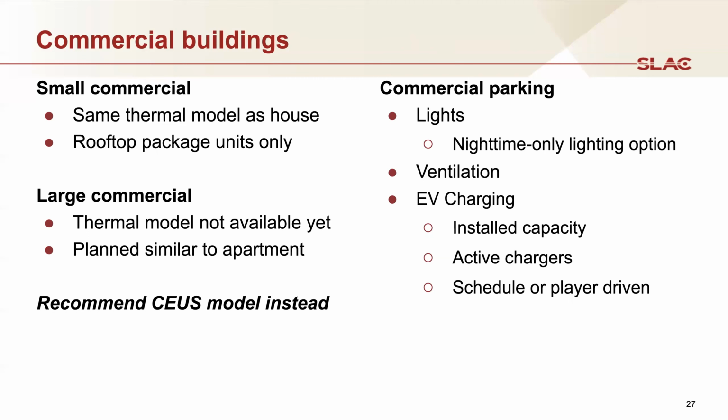For large commercial, we don't have a thermal model yet for large commercial buildings. We plan to do something similar to apartment buildings, but for now, I would just recommend using the CUS data models. The CUS data that's provided, there's a model for doing that in GridLAB-D, and it gives you commercial building loads, but unfortunately, you won't be able to implement demand response strategies with CUS unless you add those load sensitivities to the model itself.